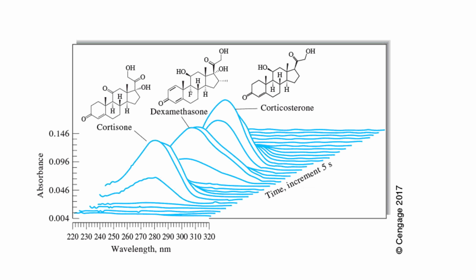Here's an example, something like what they showed us at the plant on our tour last week, where you've got wavelength versus absorbance, and in this example a spectrum is taken every 5 seconds. We can see these different cortisone-related compounds, these steroid-type compounds. Each one of them has a slightly different spectrum in the UV-vis, a different lambda max, and we could differentiate which one of those compounds it was.